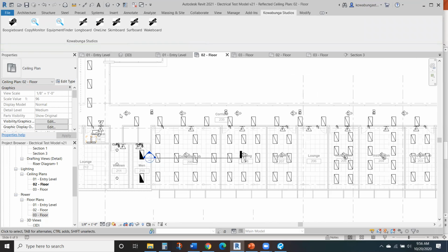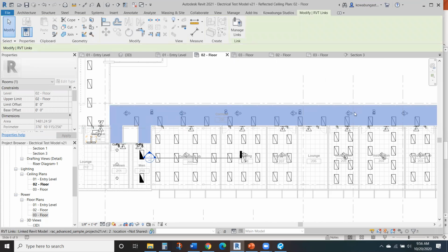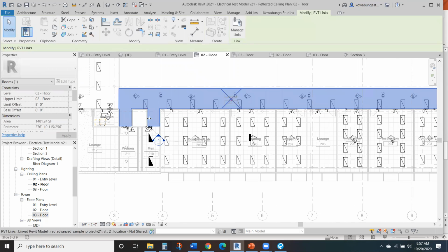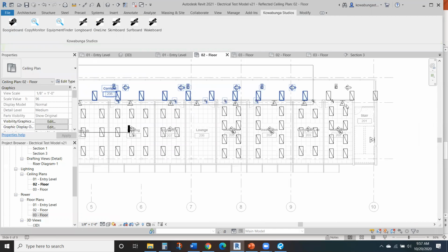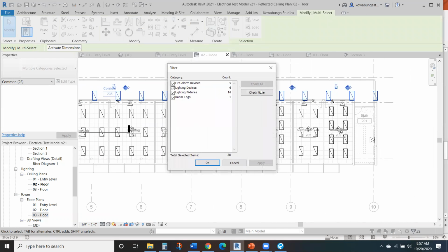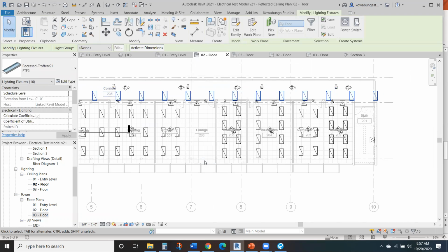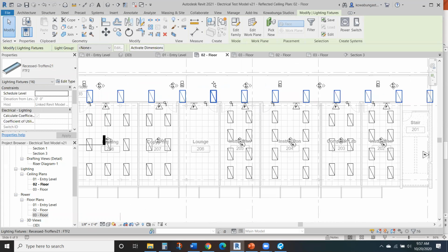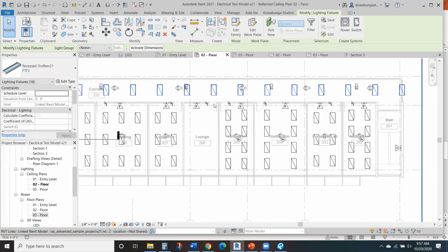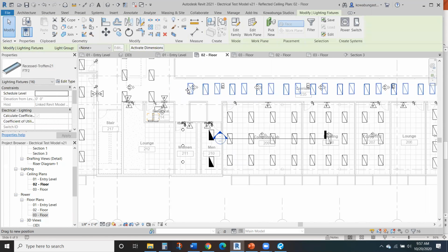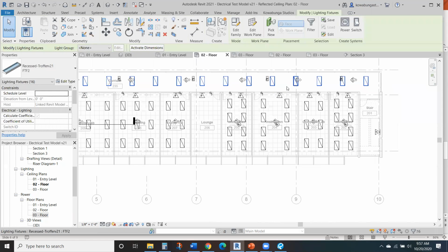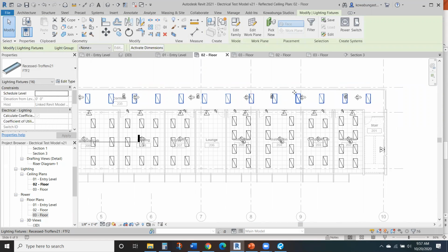So there we go. And then with like this room, you might see some adjustments here. It's because they are centered, quote unquote, in the room, but because this room juts into these little vestibule areas or alcoves, they're centered there. So there might be some adjustments where you come through like this, check none, light fixtures, right? And then we adjust them in the model to where they need to be. And again, spacing's gonna hold, all that great stuff. So we'll come through and adjust placements a little bit and go from there.